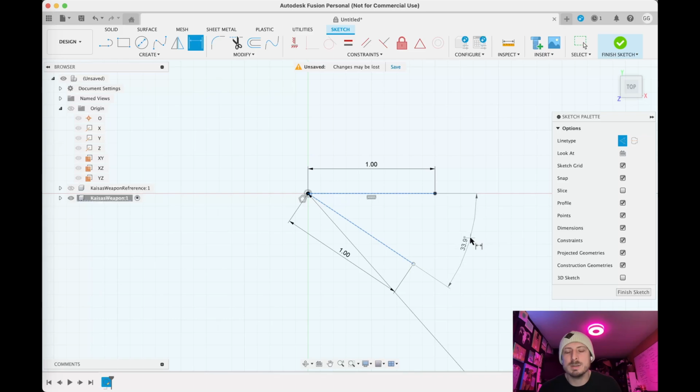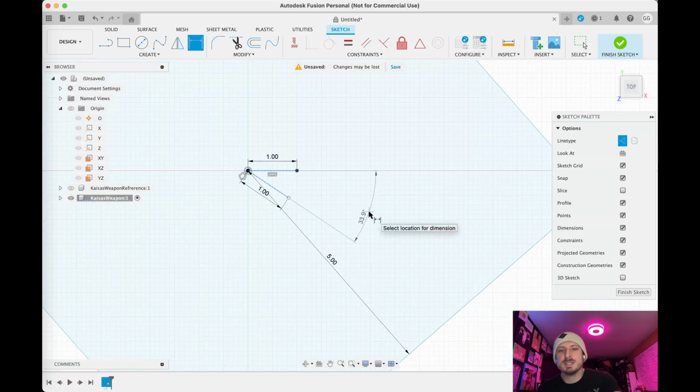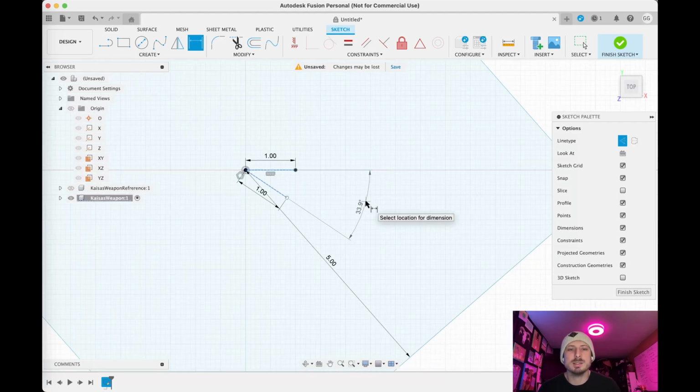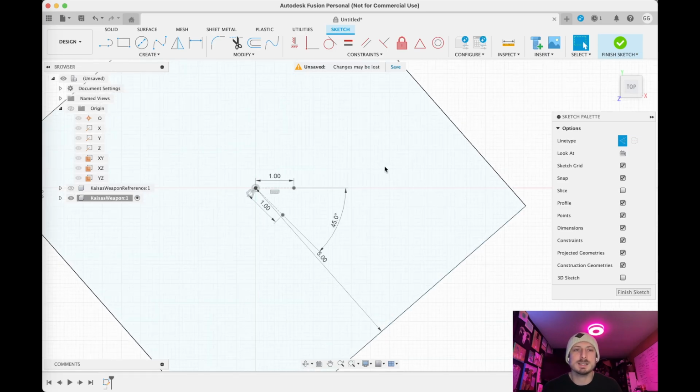There we go. So I didn't like that the measurement line, I guess this 5 millimeter line, is just a measurement. It's not an actual line, so you can't project any angles or anything off of it, which is fine. So we have this. I'm going to make this 45 degrees. And now you'll see the line pops up and it's constrained to always be 45 degrees. This first line is constrained to the x-axis. The second line is always constrained to be 45 degrees from the x-axis.